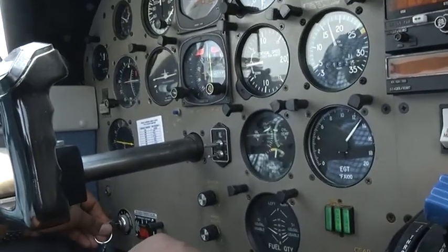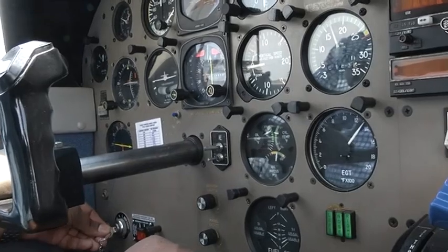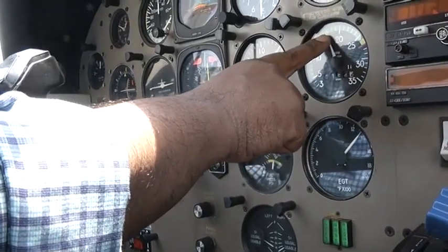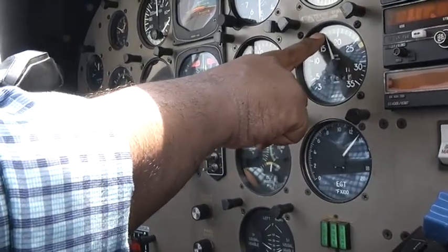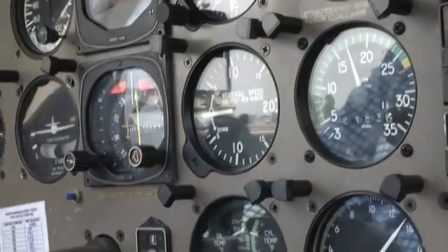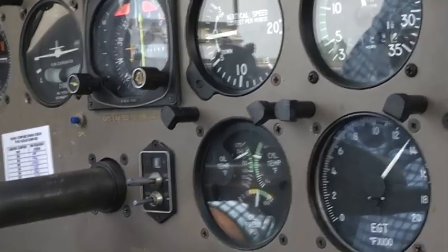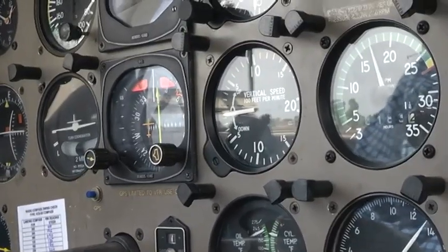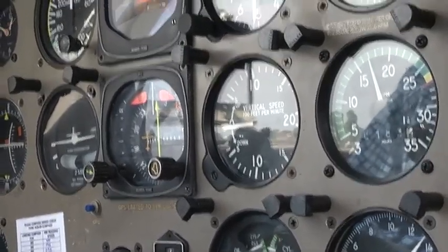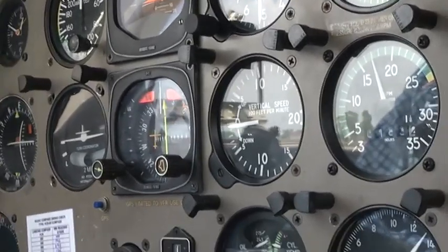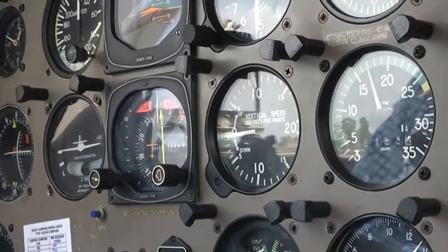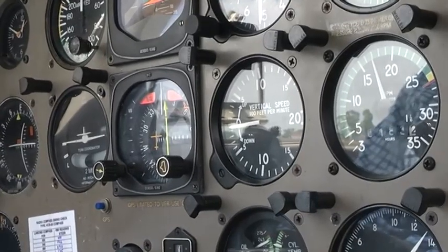See, it is from both to right. See the drop. You have seen from 1700 it came to 1600 and it's back to 1700 because the ignition key was switched to both position again. So what we observed is a drop of around 100 RPM, which is satisfactory, within the range.